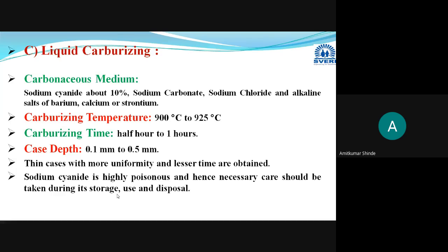If you compare all three types, solid, gas, and liquid, liquid carburizing will provide the thinnest case depth along with more uniformity and in the least possible time.